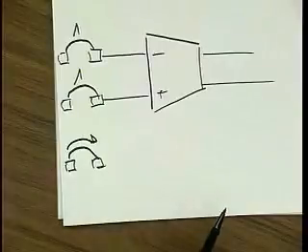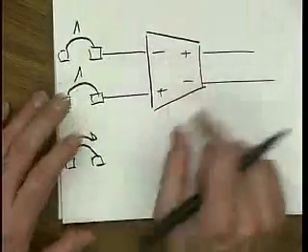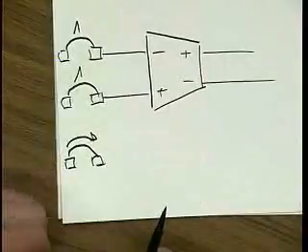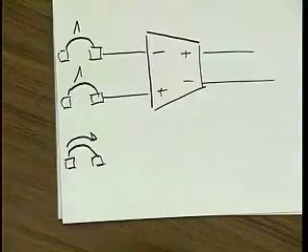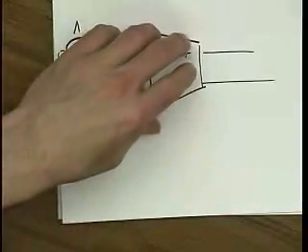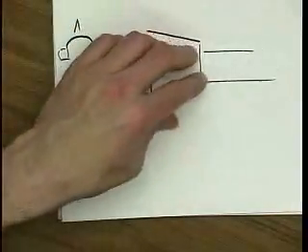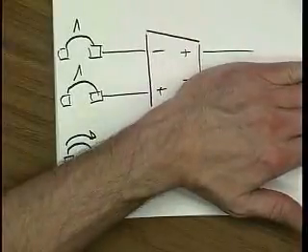And because of that, we're going to use amplifiers that have both differential input and also differential output. Now, if we think about noise, that also is an advantage, because the noise of this amplifier and the amplifier that had only one single output is about the same.